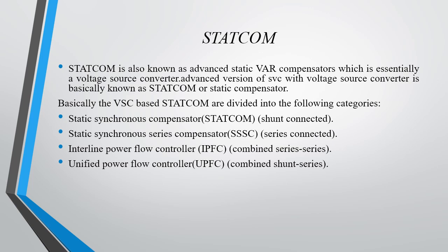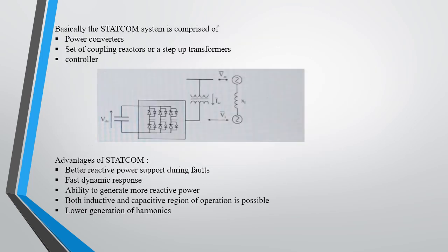That can be divided into the following categories: STATCOM, shunt connected; then static synchronous series compensator, series connected; interline power flow controller, that is IPFC; then unified power flow controller, that is UPFC. Basically the STATCOM system is comprised of power converters, a set of coupling reactors or step-up transformers, and a controller. We can see this in the circuit diagram.